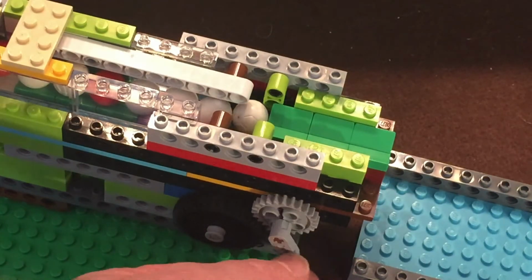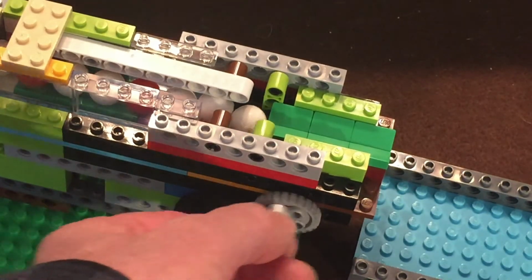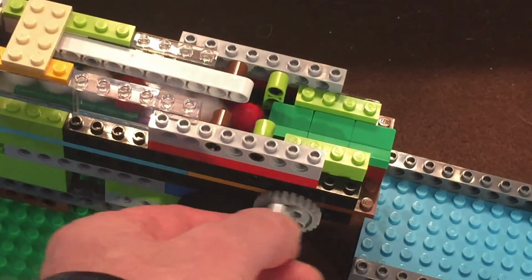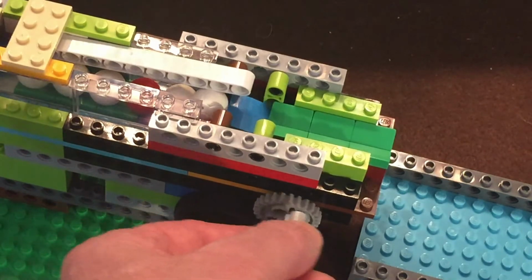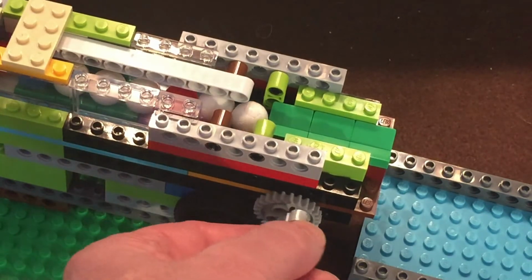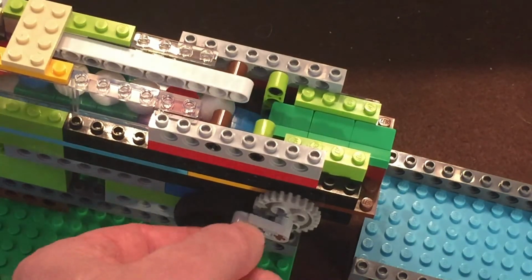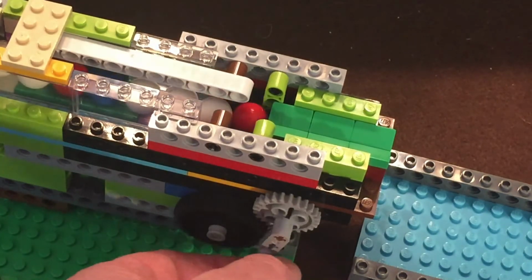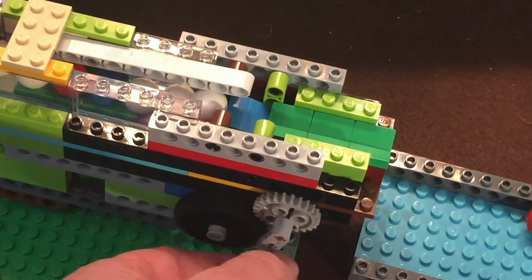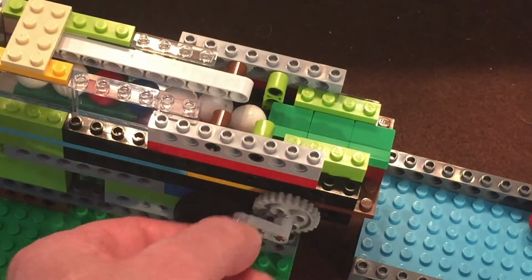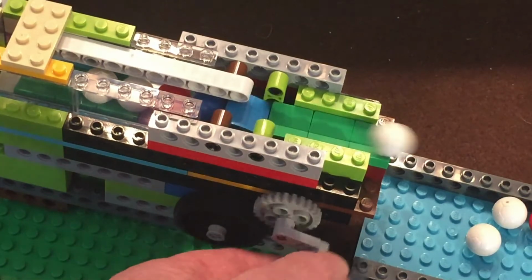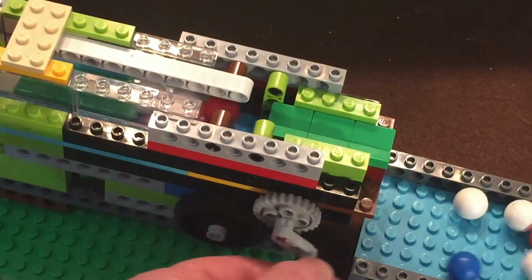This design uses a piston to lift balls up and over a stop. This design is pretty resistant to push, and there isn't anything for the balls to jam against. It also has the advantage of actually adding height to the balls, which can be helpful if the next part of the module is elevated. Unfortunately, the downside of this design is that it requires a lot of clearance underneath the track, which means the minimum elevation for the input and output tracks is fairly high.